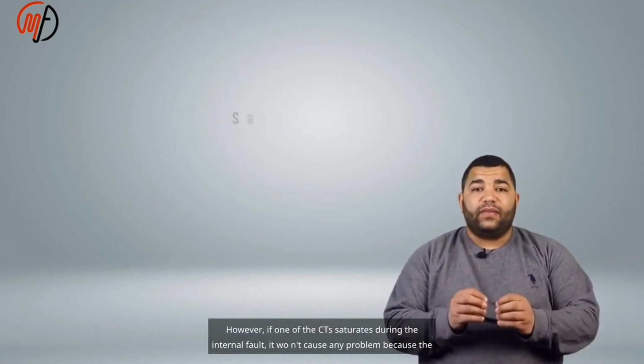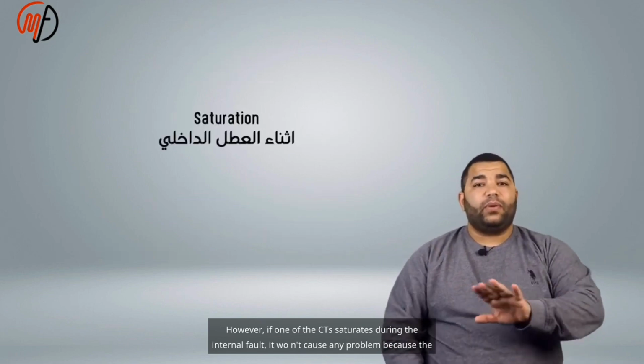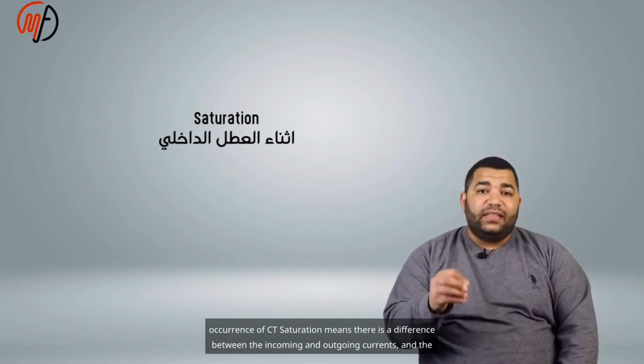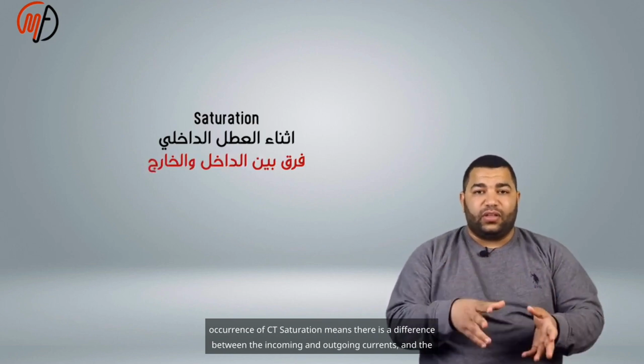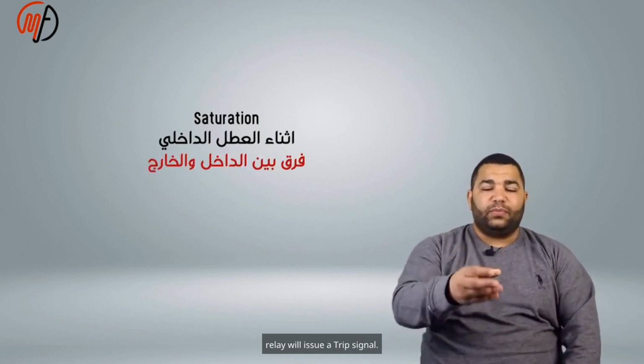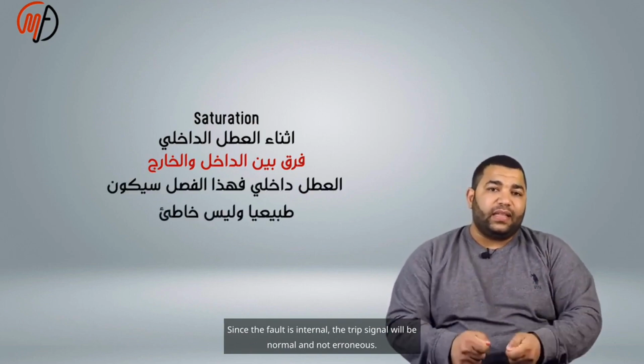However, if one of the CTs saturates during the internal fault, it won't cause any problem, because the occurrence of CT saturation means there is a difference between the incoming and outgoing currents, and the relay will issue a trip signal. Since the fault is internal, the trip signal will be normal and not erroneous.